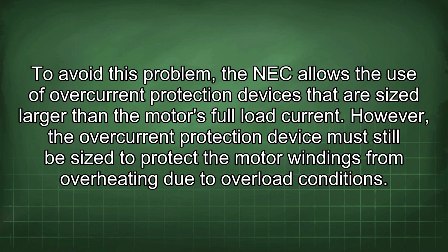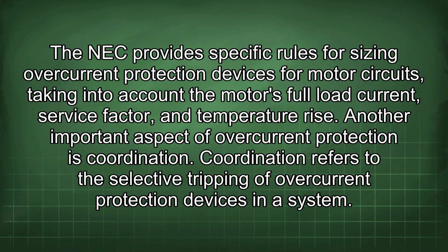full load current. However, the overcurrent protection device must still be sized to protect the motor windings from overheating due to overload conditions. The NEC provides specific rules for sizing overcurrent protection devices for motor circuits, taking into account the motor's full load current, service factor, and temperature rise. Another important aspect of overcurrent protection is coordination.